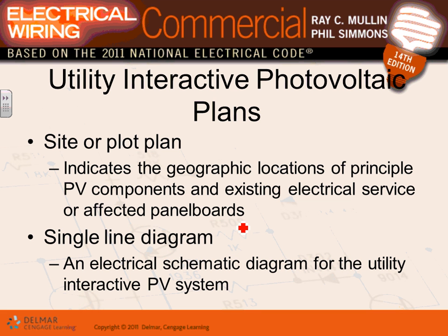You take the solar panels, you combine them together with a combiner, with multiple disconnects for safety, invert them with an inverter, and dump them into the grid so you can feed your house as well as other neighbors, with an agreement with the grid.